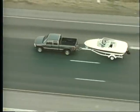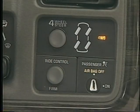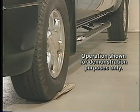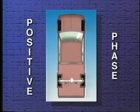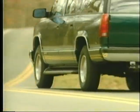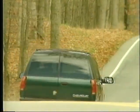The rear wheel steering system helps improve stability during high-speed lane changes. With the mode select switch in the four-wheel steer position, front and rear wheels turn the same direction during high-speed maneuvers, such as lane changes. When both the front and rear wheels turn in the same direction, the system is operating in a positive phase. Positive phase rear wheel steering improves stability during higher speed maneuvers.